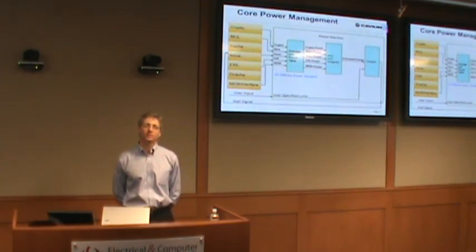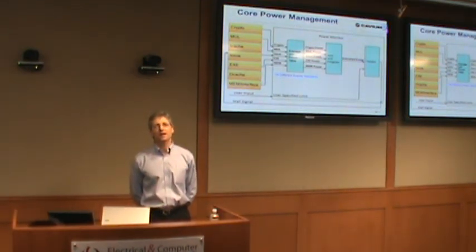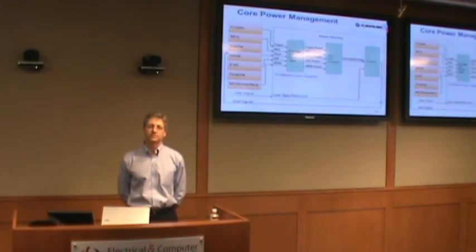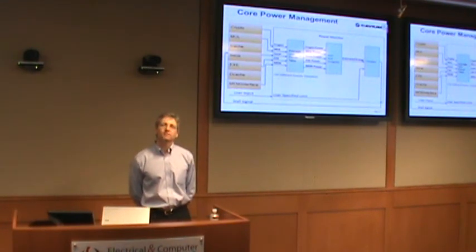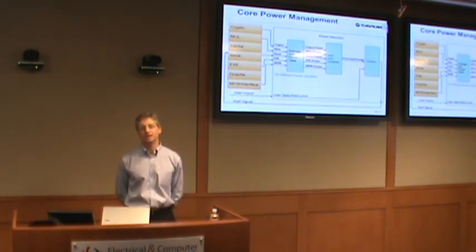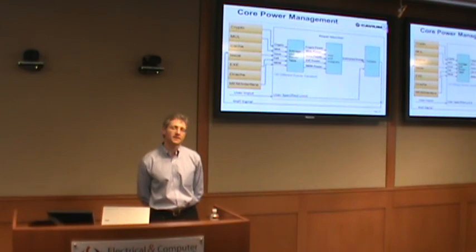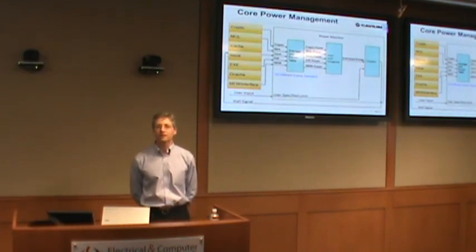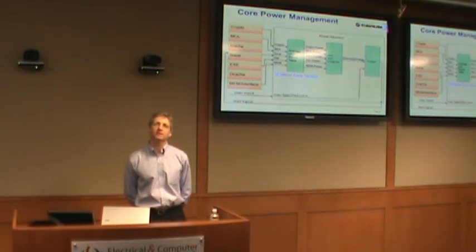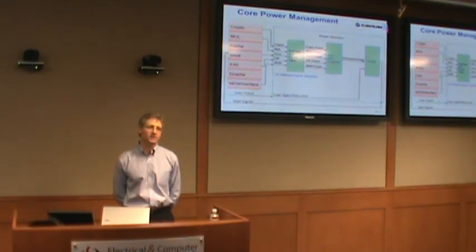The instruction issued was a load. Or this clock in the multiplier was running. That might be an event. For every event, we calculated from simulation and then validated in real hardware the amount of energy that's consumed for that event, and we put that amount into what's called here the power table.